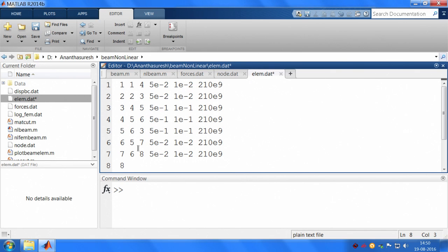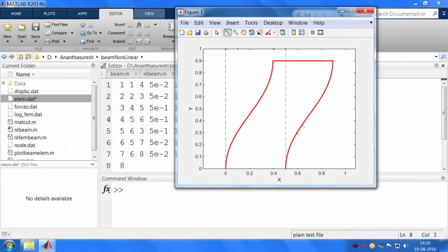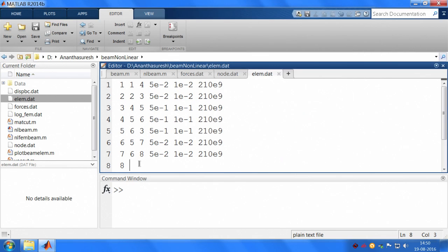that I would do. The new nodes that we created are here. So, 1, 2, 3, 4, 5, 6, 7, 8, 9. So, 7 and 9, 9 and 8, that is what you need to have rigid elements. So, 7 and 9, and this is, I would like to put 50 centimeters, okay, half a meter, and this is also 1 E minus 1.